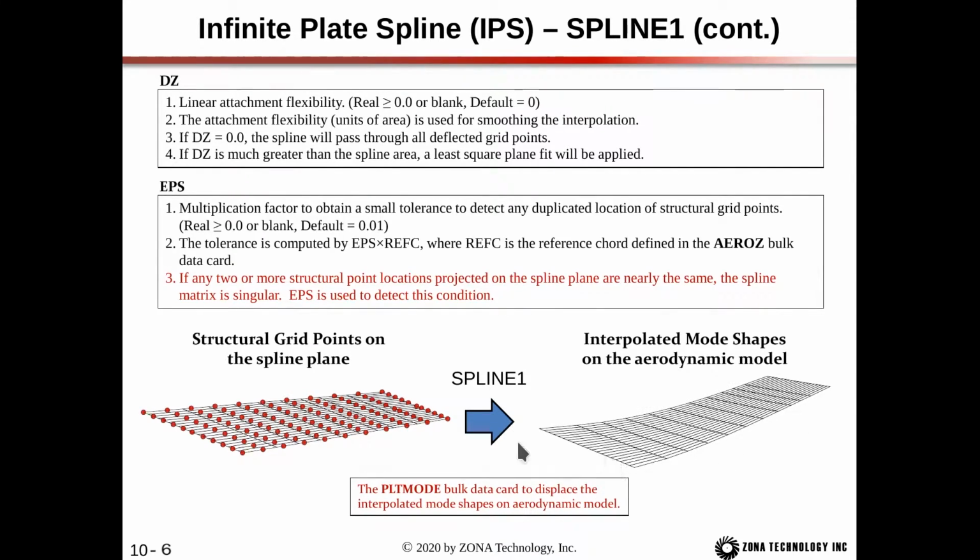The deformed structure grid points is not shown here. This is just the original structure model and the original aerodynamic model. And then here we're showing only the deformed aerodynamic model. And we're using the PLOTMODE card to visualize this displacement.